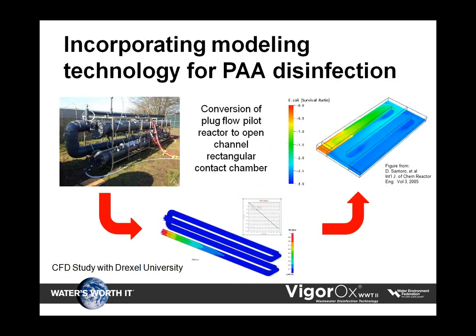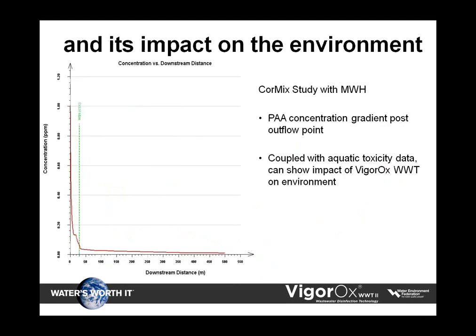The science of peracetic acid is advancing. Next generation technology will take in-house and on-site PAA assessment into the realm of computer modeling, which ultimately will be tailored to simulate the peracetic acid hydraulics and kinetics for your specific wastewater treatment plant. In addition, post-outfall peracetic acid decomposition and dispersion will be modeled to provide a site-specific estimation of the impact of peracetic acid upon the local environment.